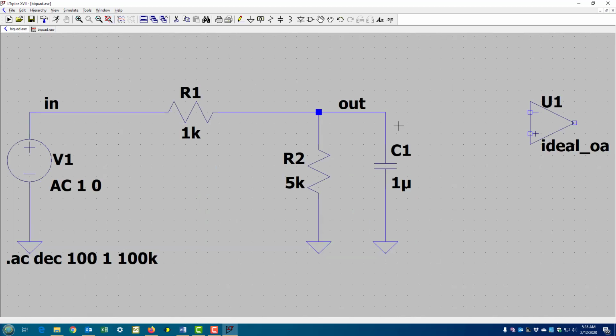Let's just wire up another simple filter. First of all, I want negative feedback, so I want to put this upside down. So let me rotate it. To rotate it, I have to either move it or drag it, so I have to click one of these buttons. Let me click move and highlight the op amp. Now I can move it around, but in this highlight mode I can also rotate it. So I can do Control R.